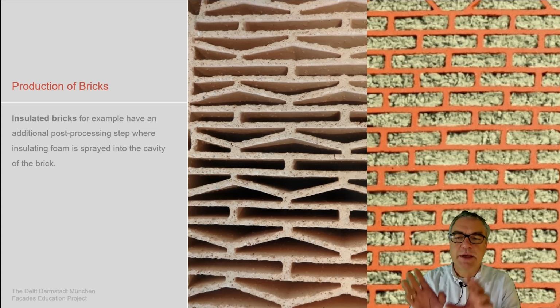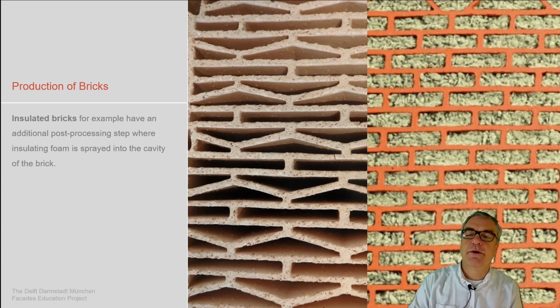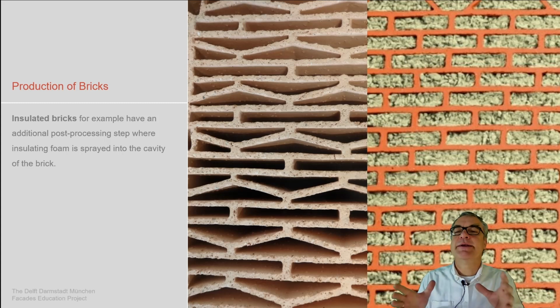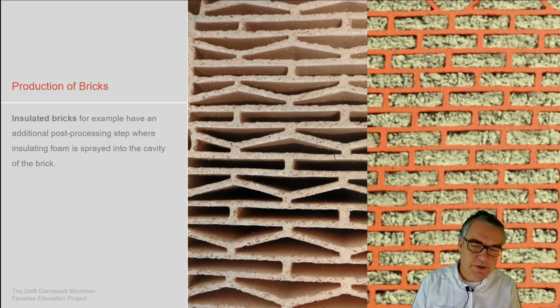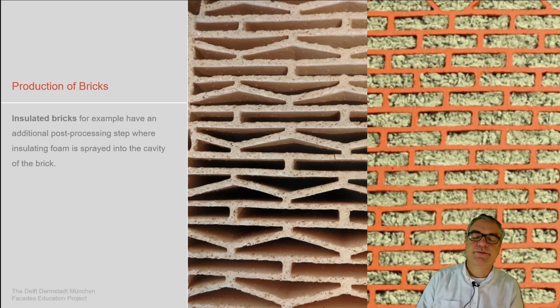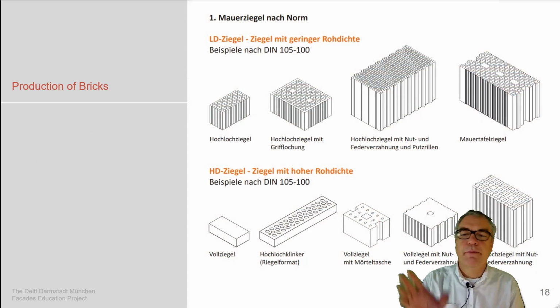We have this idea of creating solid bricks into more insulating material by adding more cavities, which we see in the left picture. And at a certain point, these cavities and making the brick lighter is getting to its limit. To then still increase the thermal performance of a brick, we nowadays often also have some insulation material in the cavities, Rockwool in this setup, to make the brick in total lighter and by that create better thermal insulation properties.